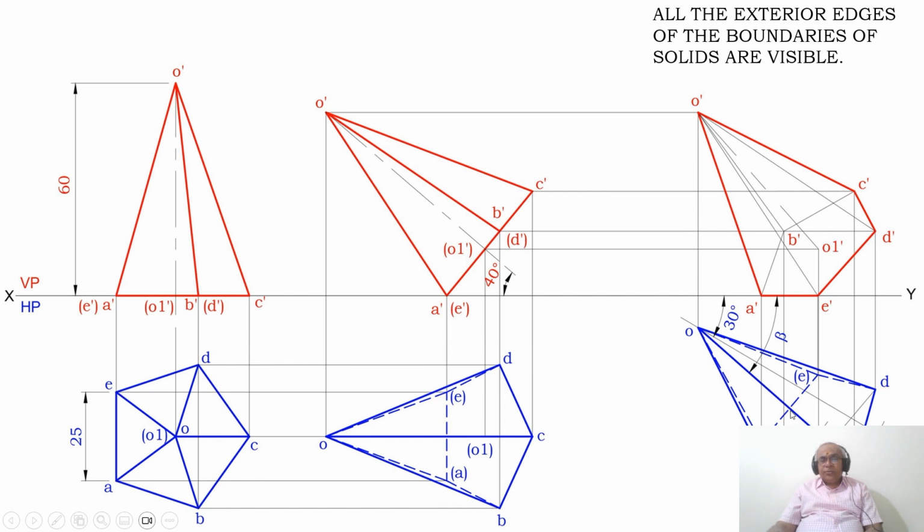Now as we see, this line is perpendicular to this OC line. So what I need to do, with reference to this point, you take the protractor with reference to this point, which is on this AE line, and draw a perpendicular to OC or O1. Then from here you draw a perpendicular and extend it on either side.